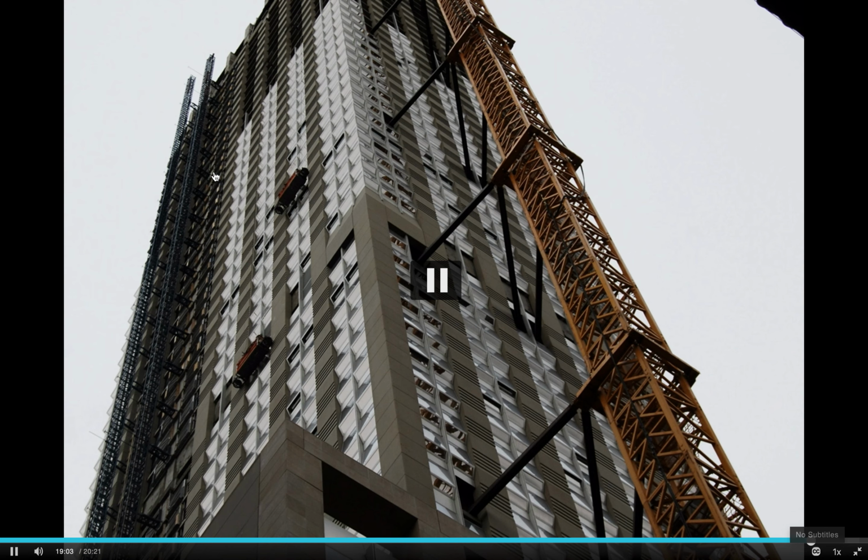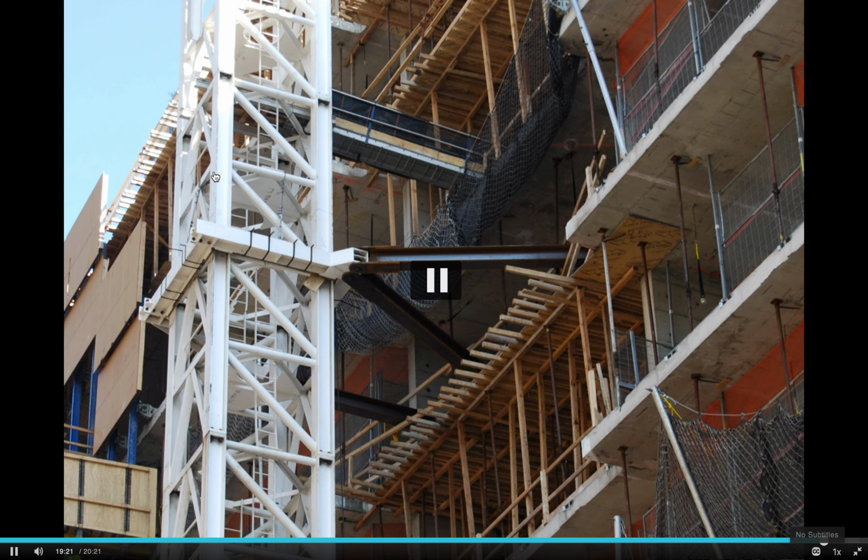That you have holes, that you have the right size bolts, that you have the proper framing and spacing. So that all gets coordinated even well before you're into construction or have any materials. It has to get coordinated from the drawing stage when they're developing shop drawings off of the contract plans. Right. So just another angle of how you tie into the building there and give that lateral support to the tower crane, the bracing.